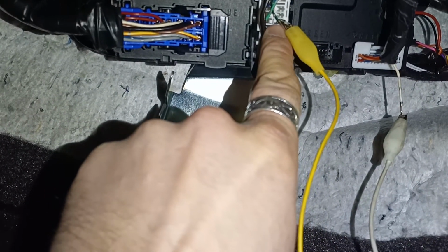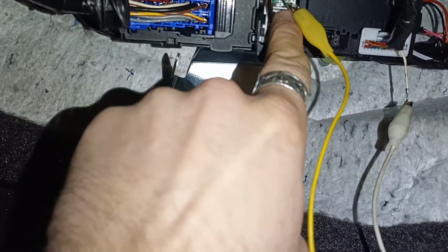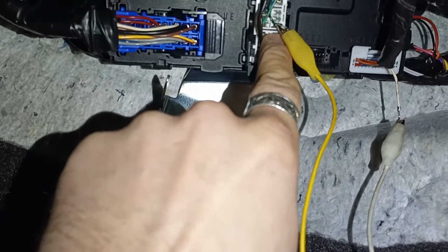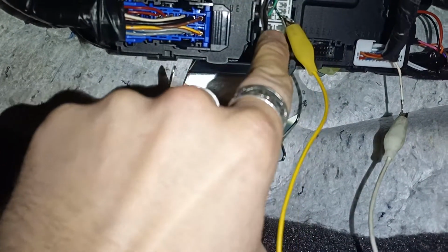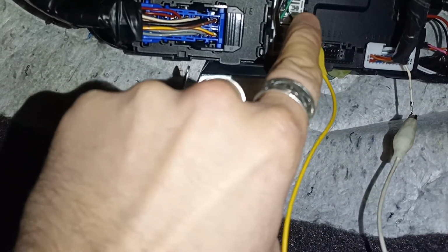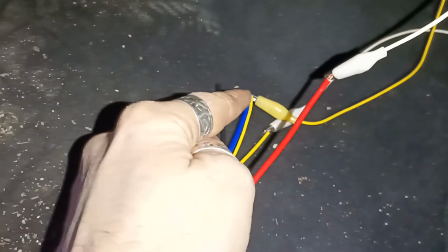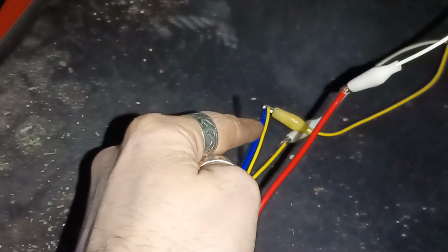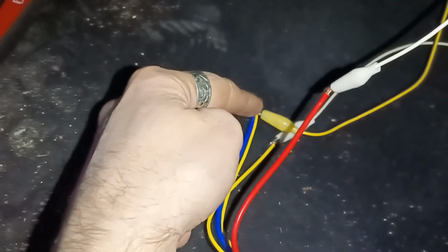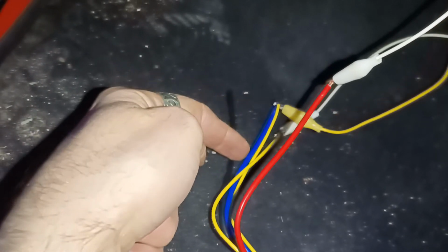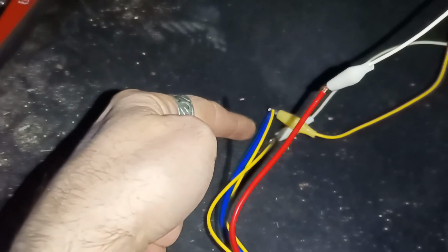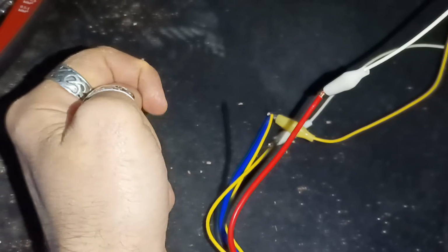When you're looking at it like that, bottom right. That's your ignition wire. So you need to grab that wire and shove it in both on the coil. You can see I have twisted the two cables, both on the coil and as a source that is going to go towards the light bulbs, the DRL.